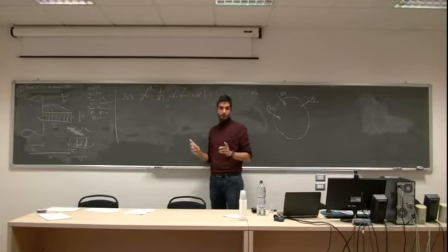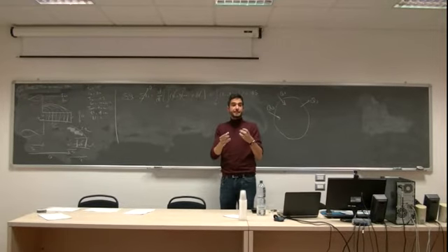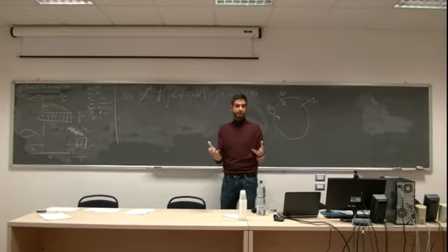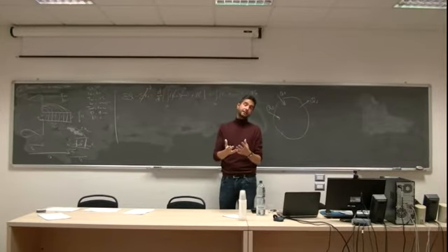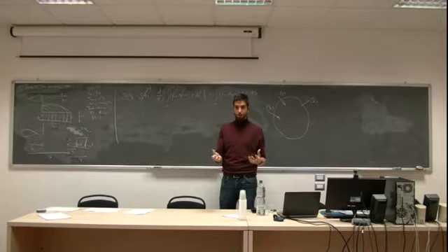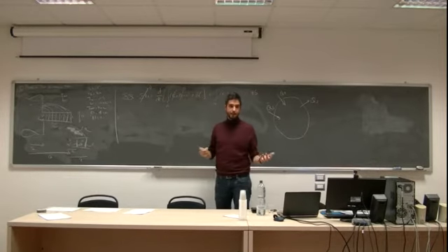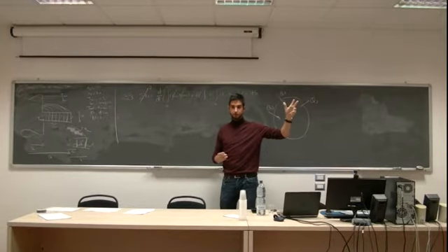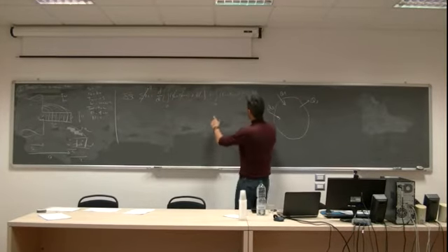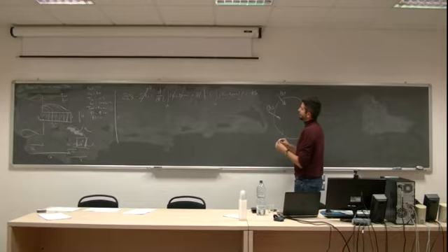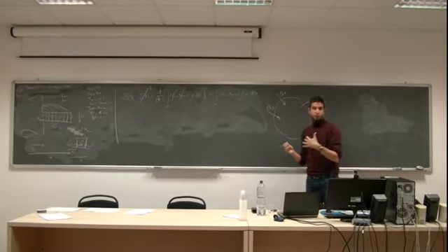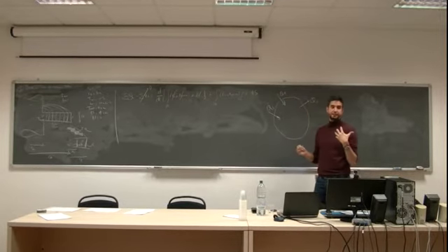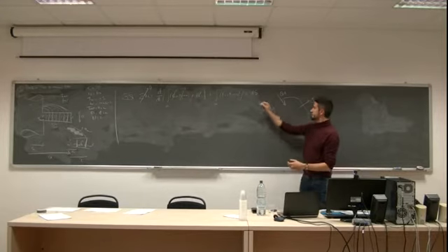This not, because your domain can change the level of energy inside it by varying its temperature, for example, or by changing phase from solid to liquid. So it has different internal energy and hence different enthalpy. You follow me? Yeah. And this term comes from mass flow going inside or outside the surface of the domain.